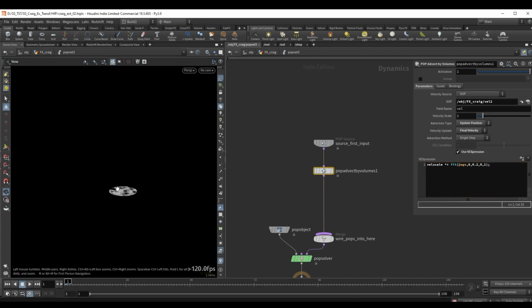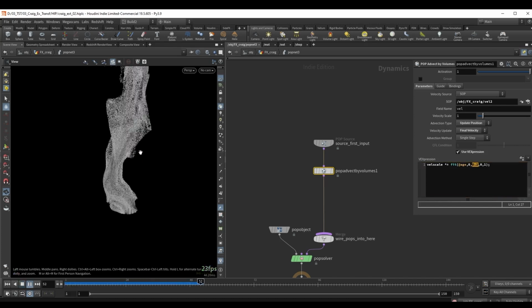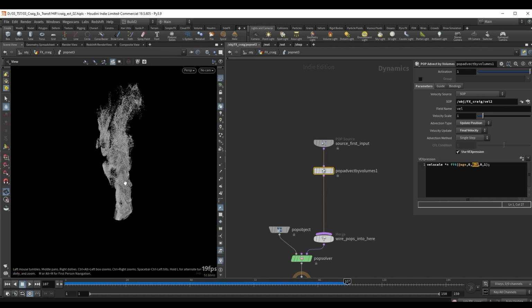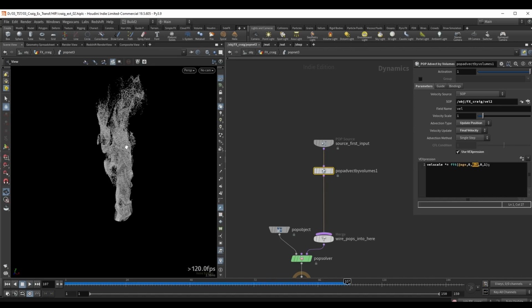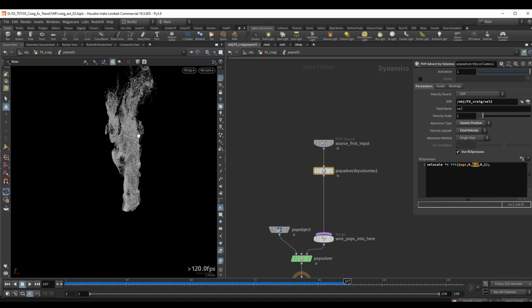But now essentially this should blend in the position. So we are mapping the velocity scale on our age. So now we are blending the velocity scale in over a time period of roughly 0.2 seconds, which is this value over here. And as a result, now we should have a smooth motion. Okay, so this is looking pretty good. And now for the second thing that we want to do here is make our particles thinner as the simulation progresses. And this is a technique explained in my volume sample and volume gradient video. So I also recommend checking that out as well if you haven't already.